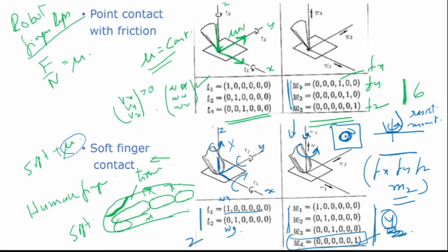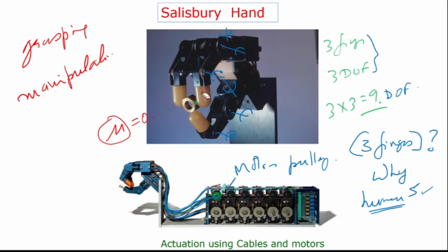So before we analyze any multi-finger manipulation, let me make a point here. If you are wondering what the relation is with motion planning or path planning, in this particular application, I want to impart a particular motion to this nut. For example, I want to tighten this nut, so I have to rotate it about an axis. To rotate this nut about an axis, I have to impart forces and moments. And rotation means I have to impart some desired velocity. So that is what this analysis is going to tell us: the relationship between the fingertip forces and moments and the resultant velocity of the object.